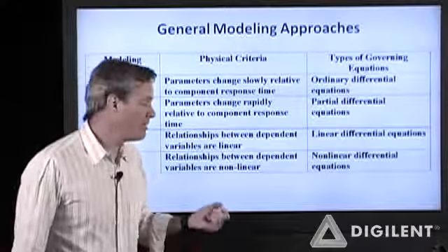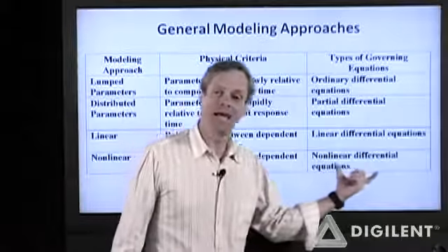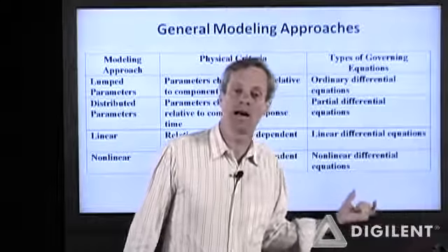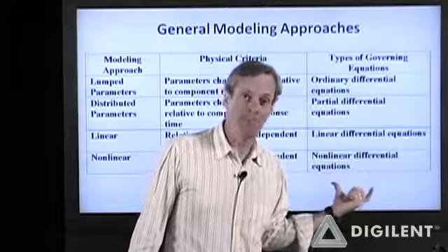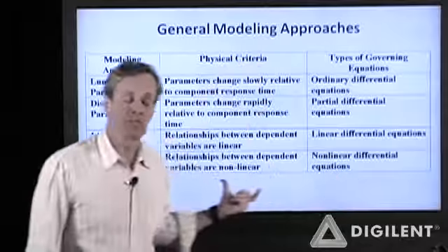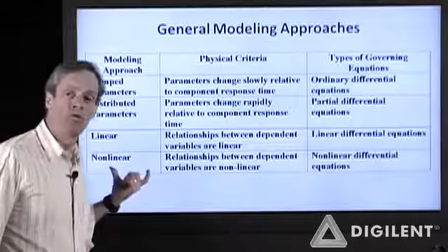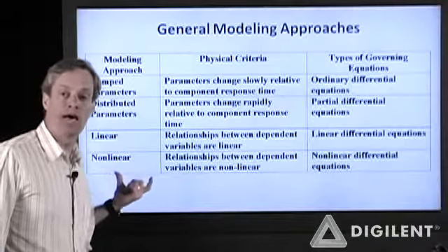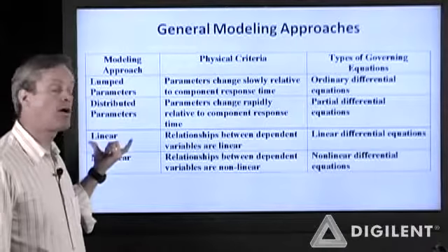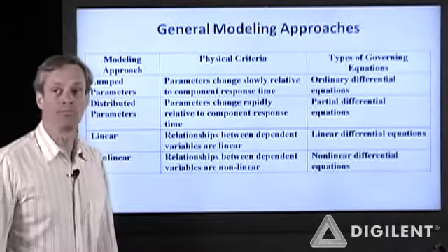More than one solution implies that the system can operate at more than one point. So you may design this system to operate at some point. If it's nonlinear, it may decide to go ahead and operate at some other point, which you may not be very happy about. We'd much rather design linear systems than nonlinear systems. These are tough to deal with. The problem is that any real system is ultimately going to be nonlinear to some extent. What we tend to try to do is take a nonlinear system and approximate it as a linear system, design to that, and hope that everything works out.